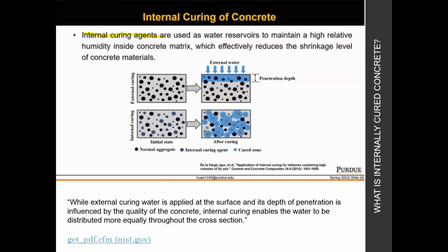And there is a similarity there between the lightweight pre-wetted aggregates and what we're doing today, whether that might be with cellulose fibers, nanomodified cements, certain types of nanosilicas. A lot of these, silica, even at the nanoscale, it's still a rock, and it's still going to have that water around it. Obviously, the scale impact is different.